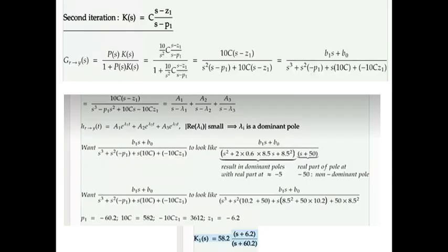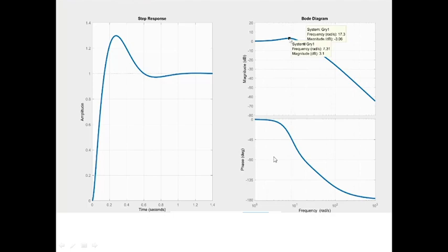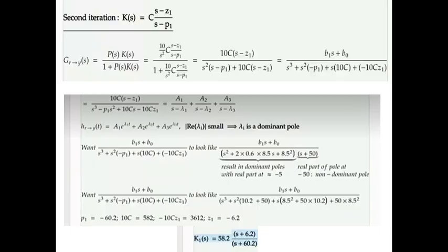In this case we had chosen the dominant solution with zeta 0.6 and omega n equal to 8.5. One choice is to increase zeta, since we had seen that on increasing zeta the overshoot generally decreases. A second observation is similar to the practice we did in first order: to reduce b1, that is to reduce 10c.